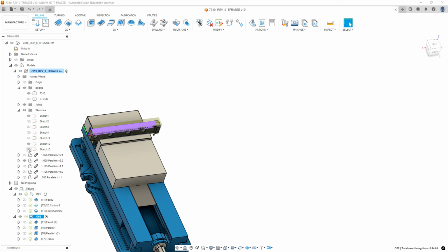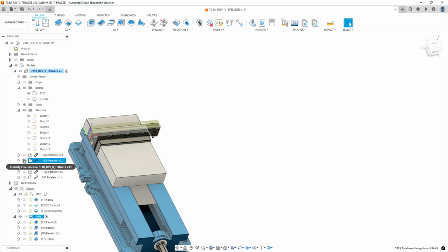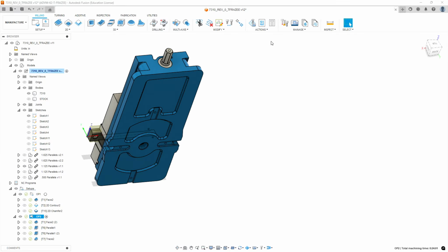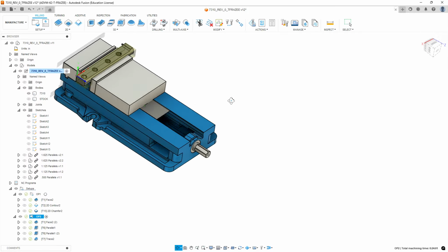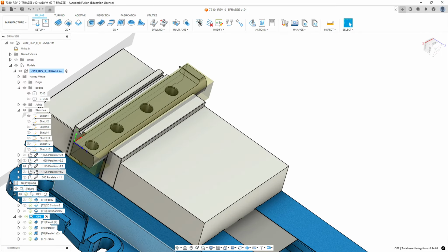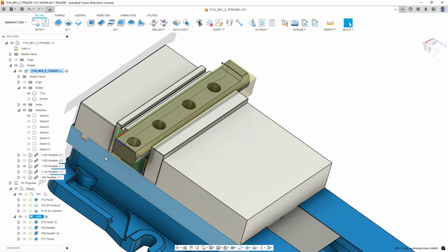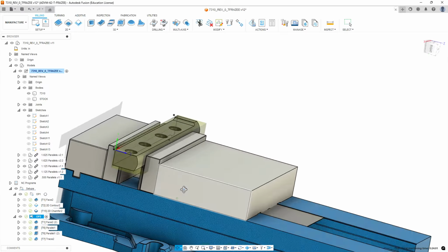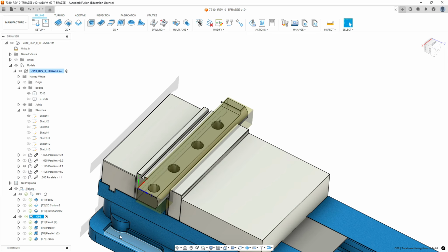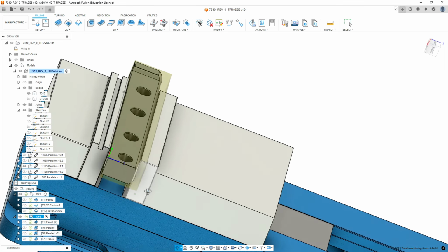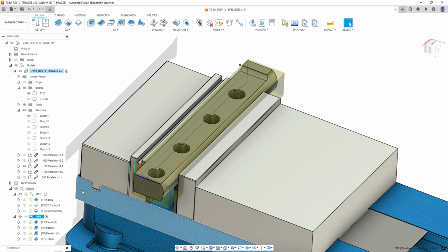Okay, operation 3. Go ahead and hide the sketch for the engraving since we're done with that. We're going to hide the current vise setup and move on to operation 4's vise setup. Again, this is a shorter parallel, so you need to keep track of this when you run it. The 1 5/8 are the tallest we have. There's one set at each machine. The other parallels are in a set that you in a red box, and you'll have to ask for them. We're going to keep control of that so we can double check your work.